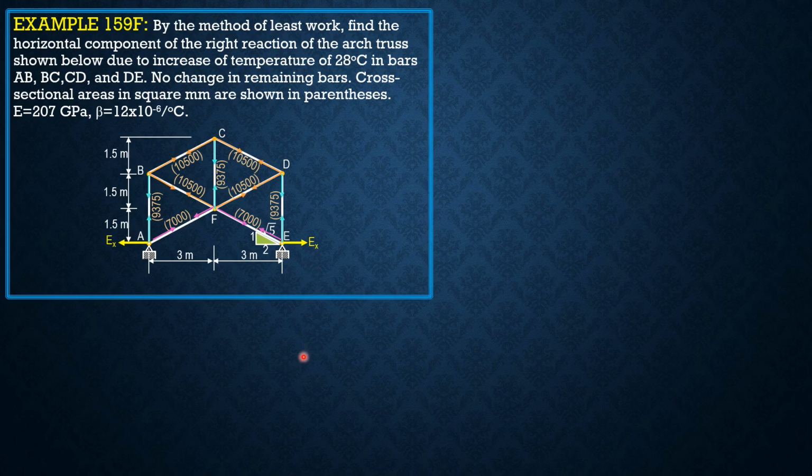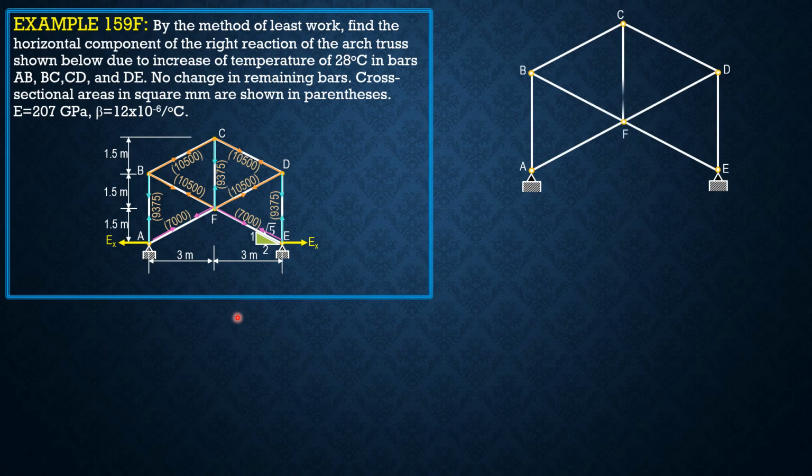As mentioned in the preceding slides, the statics will be left to you to verify. So I'll just put the values here. We analyze only the left half because the truss is geometrically symmetrical, and we need only to analyze the left half or the right half. So here is the left half.